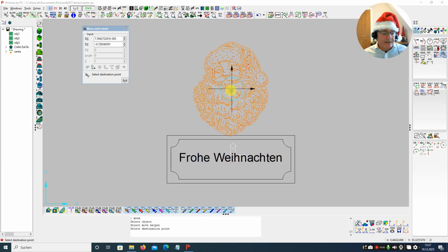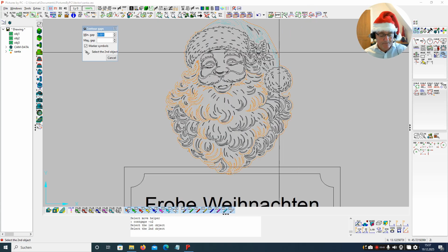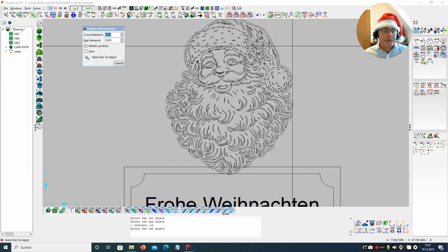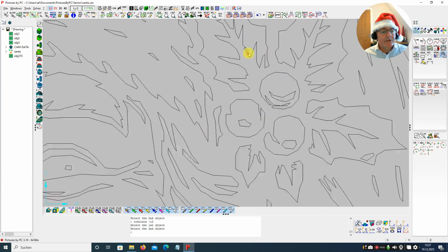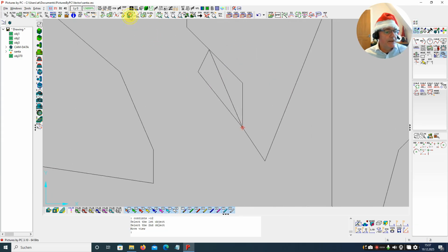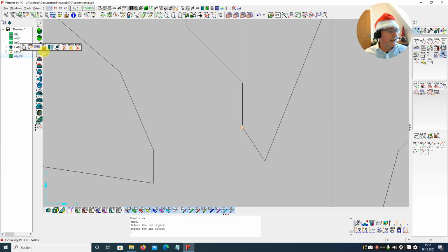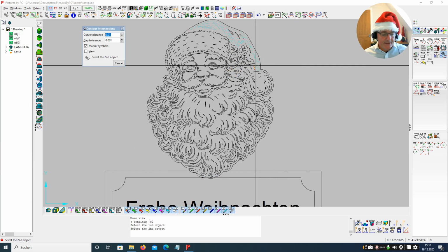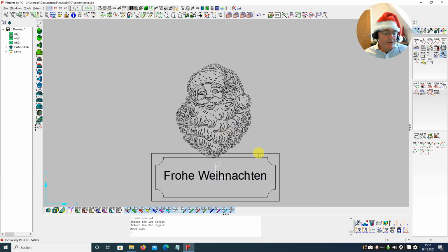What we should also check is if the contour has got any gaps in it. So let's check for gaps. No gaps. Let's check for intersections, or if we've got contours that overlap. There we've got two intersections, so let's zoom in. We can see here the pocket. Here we've got two pockets with the same endpoint, which could cause problems for the machining. So I've removed the smaller one, and we'll just quickly check again that that's okay. Brilliant. So we've got the two outside contours here.